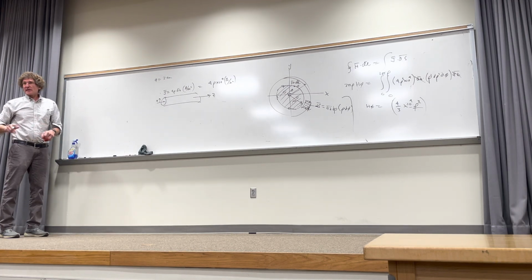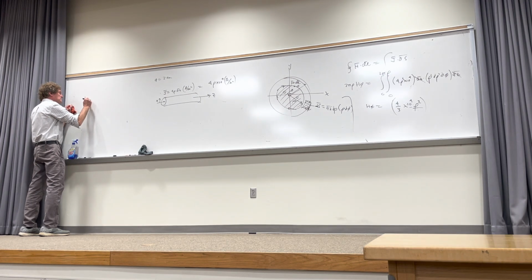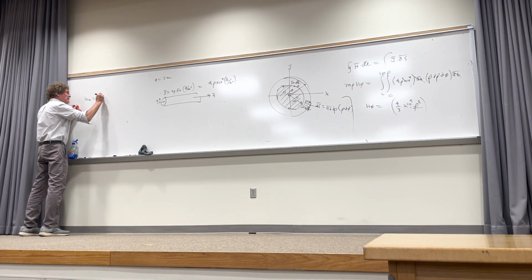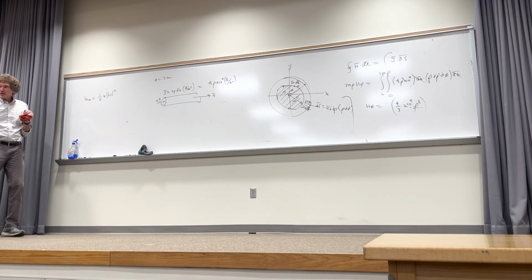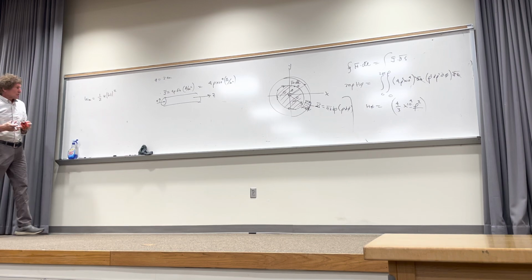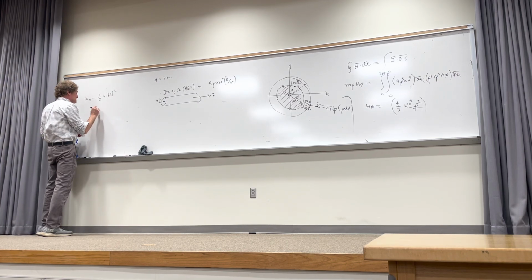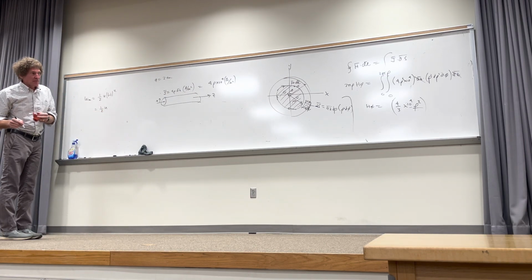Okay. Now how do I get the energy density? That's the next part. It's 1/2 mu H squared, right? Magnitude of H squared. Do you all agree with me there? It's important you see this, right? All right, so that means the energy density is 1/2 mu times H, and now I square it.